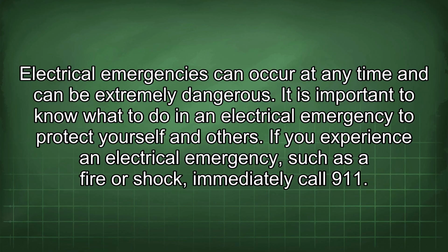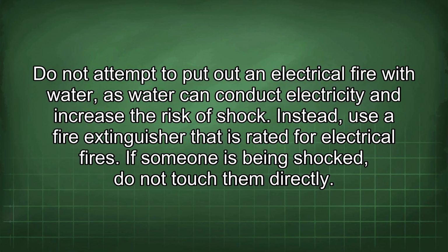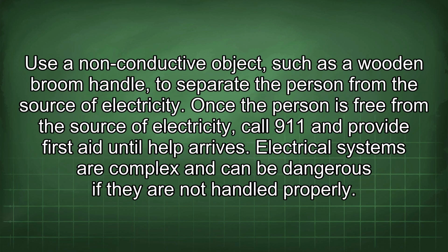If you experience an electrical emergency, such as a fire or shock, immediately call 911. Do not attempt to put out an electrical fire with water, as water can conduct electricity and increase the risk of shock. Instead, use a fire extinguisher that is rated for electrical fires. If someone is being shocked, do not touch them directly. Use a non-conductive object, such as a wooden broom handle, to separate the person from the source of electricity. Once the person is free from the source of electricity, call 911 and provide first aid until help arrives.